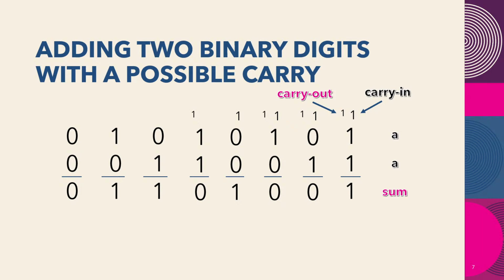And if you have 1 and 1 to add with no carry, then the result, just like we showed before on the previous slide, is going to be 0 with a carry out, a carry bit over to the next column. Now the rest of these are the same values down here on the bottom, but we're considering with the carry in operation for them.